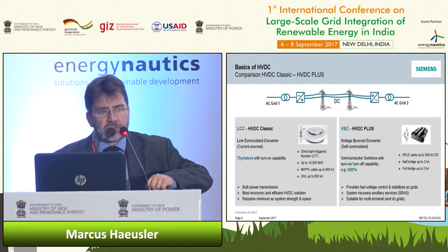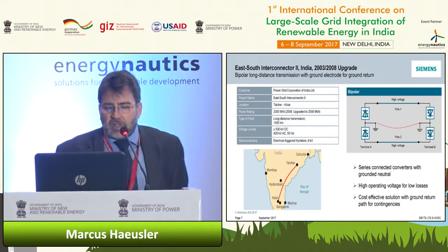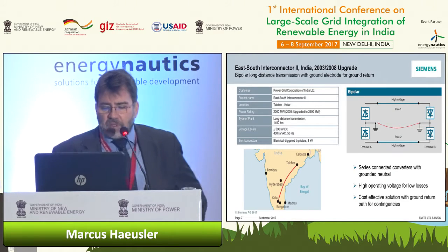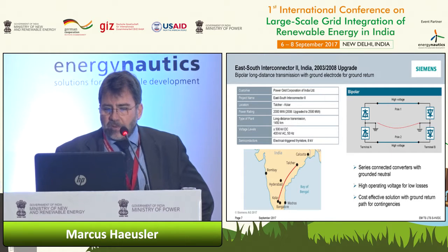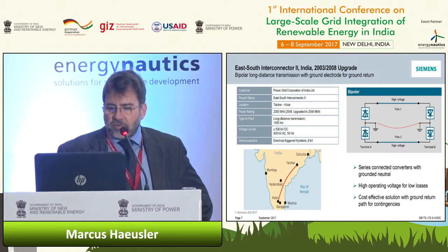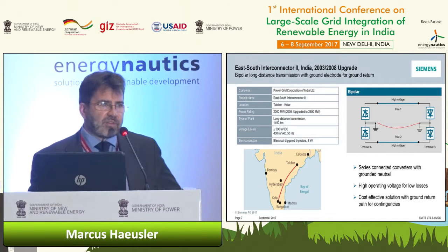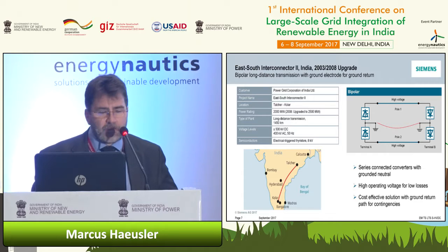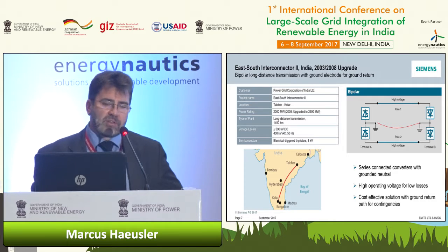I would like to first give you some examples of the thyristor technology, LCC. There's one link in the southern part, the east-south interconnector of India, which Siemens constructed, and the configuration, which is most common in LCC schemes, is a bipolar link. So we have 2 conductors, plus minus, bipolar voltage, plus minus 500 kV in this case.